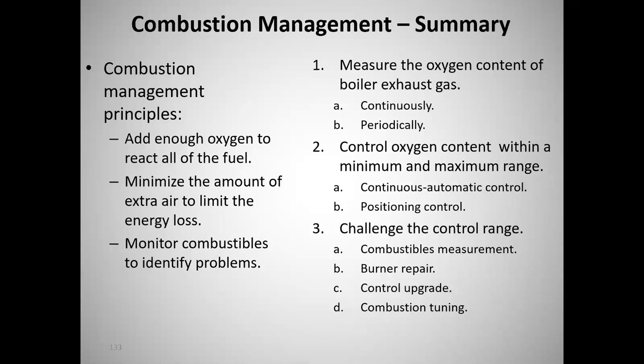Now, how much do you need? Well, that's a good question. The way to tell is to put that combustion analyzer in the stack and start periodically reducing the amount of combustion air at a given firing rate. See how low you can take it before you start seeing unburned fuel. You start seeing CO jump up, you start seeing hydrocarbons jump up. That's the limit. We can tolerate a little bit of that, but not a whole lot. And that's what sets the real limits on what's possible in a given situation.